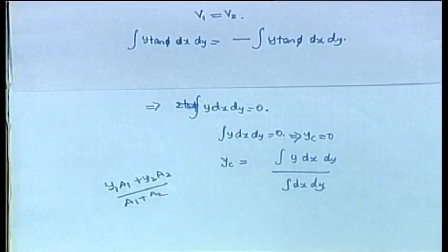Now, always when you have a ship, if you have a ship like this, and you have the water plane at some point where the water starts, there will be a surface of the ship at that point, right. That is called the water plane area, I have already told you. Now, somewhere between you will have the centroid of that water plane area, that is called the center of flotation. Okay.